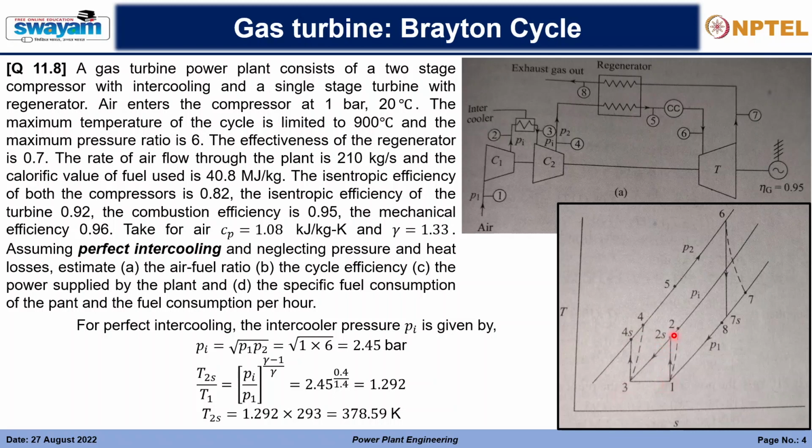And in a perfect intercooling case, T4s and T1, T3, T2s, T4s, T2 and T4, everything will be the same, obviously, if we consider the efficiency of each of the compressors to be constant. The T4s and T2s will be constant. T4 and T2 will depend upon the efficiencies of each compressor, and accordingly, if these are constant, then T4 and T2 will be equal.